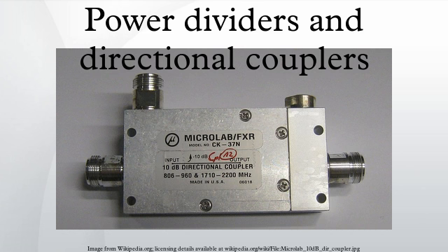If the isolators in Figure 20 are neglected, the isolation measurement determines the amount of power from the signal generator F2 that will be injected into the signal generator F1. As the injection level increases, it may cause modulation of signal generator F1, or even injection phase locking. Because of the symmetry of the directional coupler, the reverse injection will happen with the same possible modulation problems of signal generator F2 by F1. Therefore, the isolators are used in Figure 20 to effectively increase the isolation of the directional coupler. Consequently, the injection loss will be the isolation of the directional coupler plus the reverse isolation of the isolator.